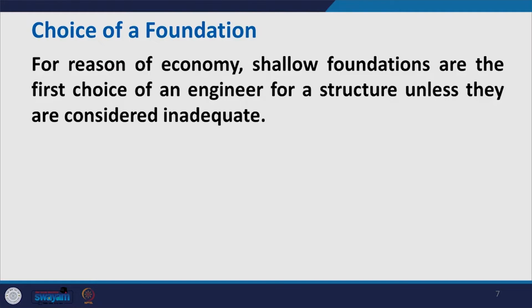Choice of foundations depends on the requirements, and it is not easy because it depends on many factors. It will depend on the type of loads coming, it will depend on the type of soil, and it also depends on your objective for which the foundation is designed. However, for reasons of economy, the first choice for an engineer for foundation is shallow foundation, because given the same situation, the shallow foundation is more economical compared to other types of foundations. Therefore, as far as possible, one should use the shallow foundation even when earthquake loads are considered, provided that shallow foundation is adequate. If we find that shallow foundation is not adequate, then only we go for other types of foundations like piles, piers, wells, and other things.